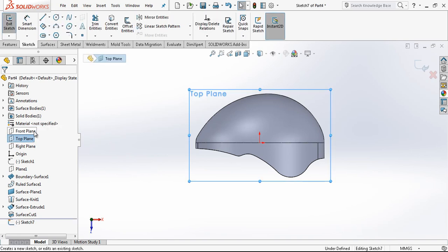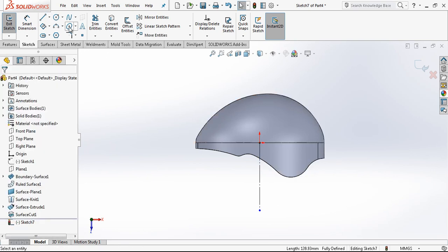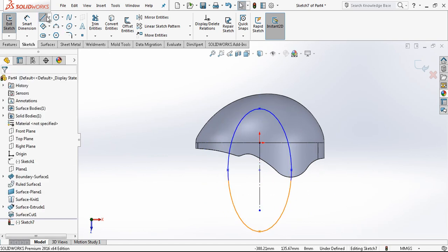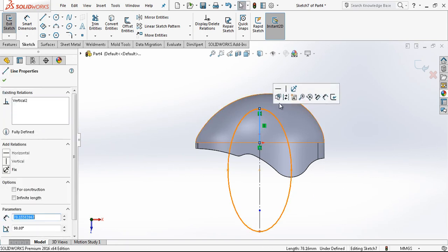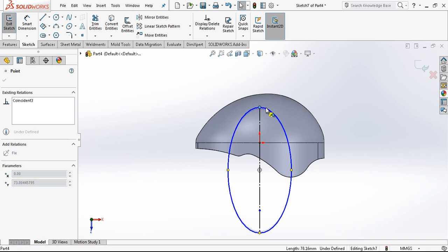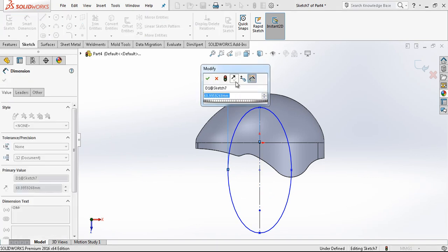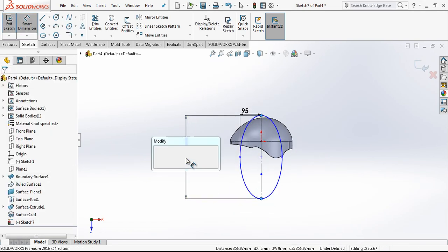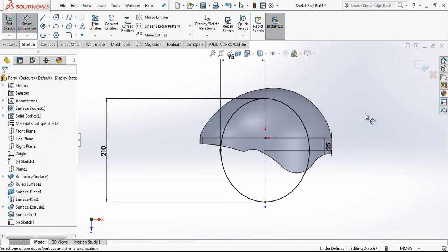Let's cut our inner form. It will be one ellipse form. To easily control them, I'm adding construction lines again. In any case, there will be the vertical. Here is 195, if I'm remembering. The value here will be 210, and our distance from here to there is 25.